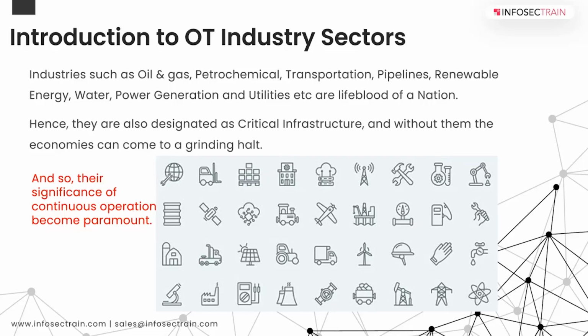Then we have batch manufacturing. When we talk about batch manufacturing, this is very distinct when compared to the process industry. Here, the processing steps are distinct. They're conducted on a quantity of material, and there is a distinct start and end step to a batch process, right? For example, pharmaceutical, paint. These are called batch processes, and there's a possibility of some steady state operation during intermediate steps.